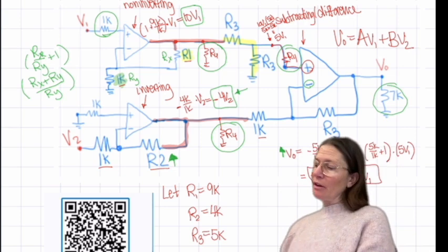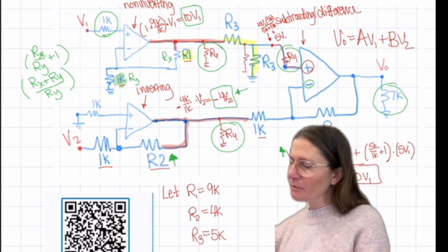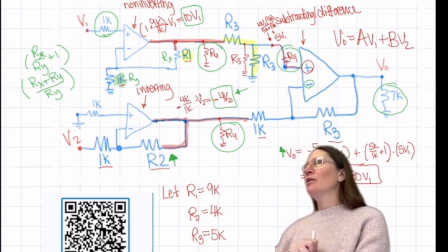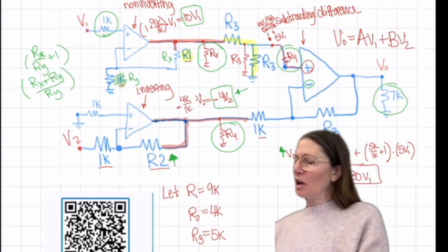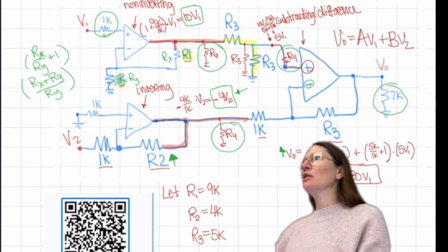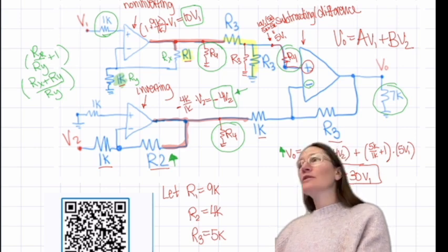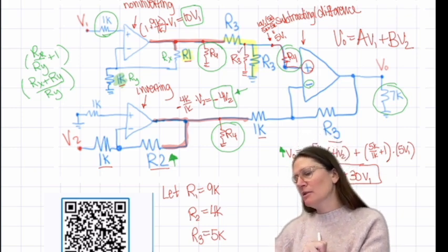Some of the other things, like if I put a resistor in parallel, so what would happen here if I put another R3 there? I mean, you probably have to include that in the equation, yeah. Correct? And that would affect it, right? Yeah. Because it would change that voltage division, and you would actually have more than just half. It would be more than 5V1. It would be an increased value there. So with that, you have to see, yeah, it will affect it somewhere. So this one will affect it.